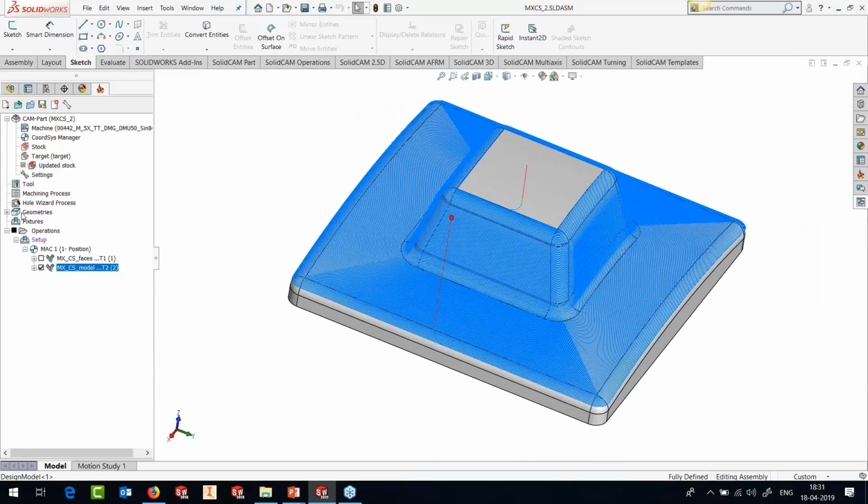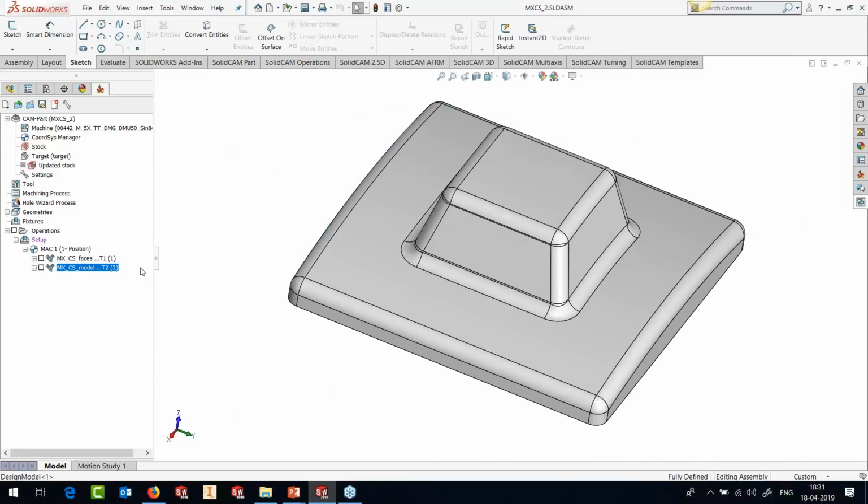So you can see now the applications where all you could apply this scenario. Like I said, any parts that you have done with parallel to curve or morph between two curves, you can easily substitute it with multi-axis constant Stepover, provide multiple surfaces including fillets, and it will give you very good results. You don't need to split geometries and do all those stuff that you would do probably with generic 5-axis.